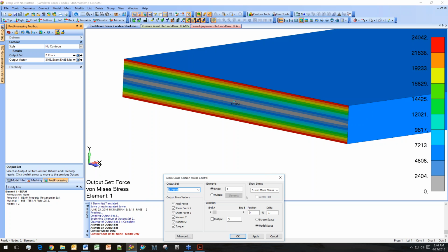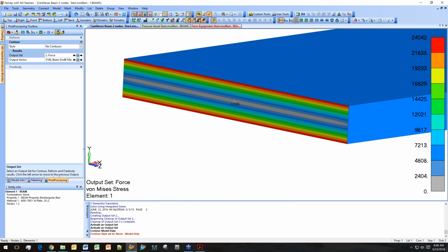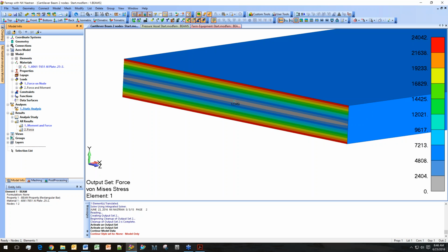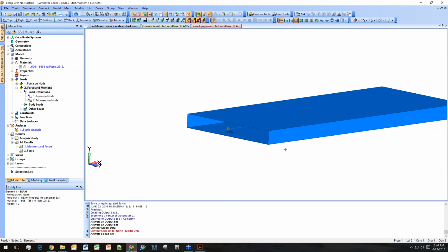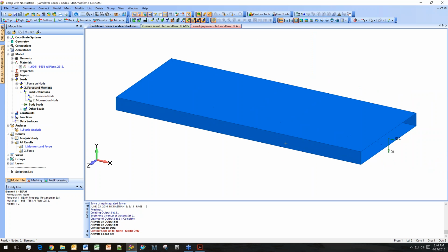And so that's interesting. That makes sense. Okay, so if we want our von Mises in our beam elements, we can just contour our max stress and call that our von Mises, or it's comparable to our von Mises. The area that this gets dangerous is, let's say your system has torsion in it.